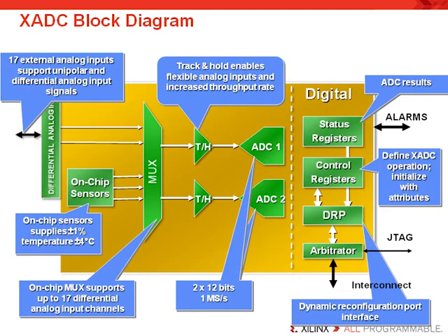The XADC core is the basic building block that enables Agile mixed signal functionality in the 7 series FPGAs and the Zynq EPP. The XADC core can access up to 17 external analog input channels. There is a single dedicated analog input pin pair, the VP-VN pair, available on the Xilinx package, and the remaining 16 auxiliary inputs use the dual-purpose I/Os on the FPGA. Now, these FPGA digital I/Os are individually nominated as analog inputs when the XADC core is instantiated into a design.